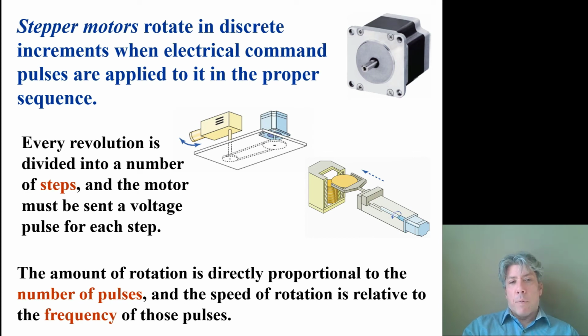So the speed is just proportional to the number of pulses. You give it pulses basically to move it from one set of coils to the next, and the speed just depends. Now, you can send pulses too fast so that the motor mechanically can't follow the desired speed. There can be over-torque situations where the motor can't provide the torque you're asking of it because the load's just too high. Or you can have inertial effects where you've applied too many pulses too fast and the motor simply can't accelerate that quickly. And it turns out that the faster these motors turn, the lower torque output they have too. So that's another potential problem.